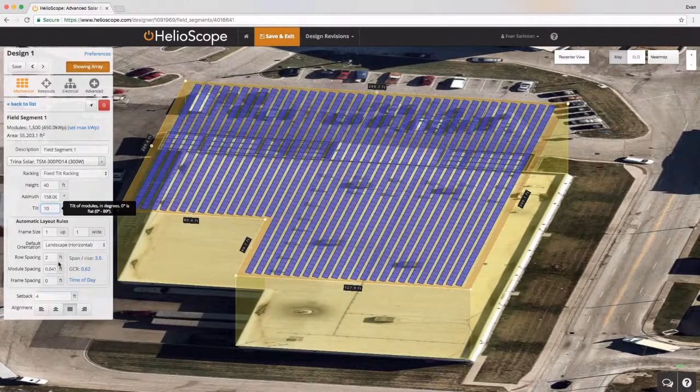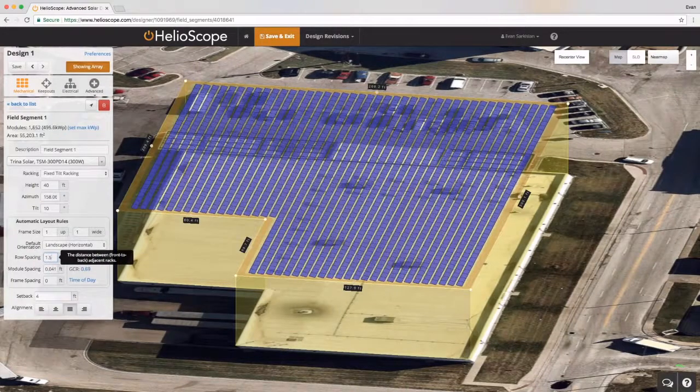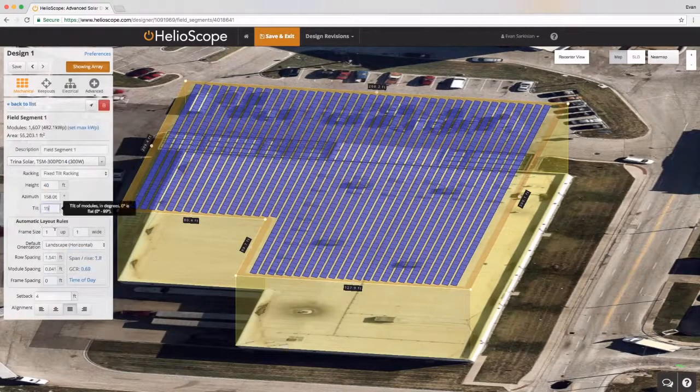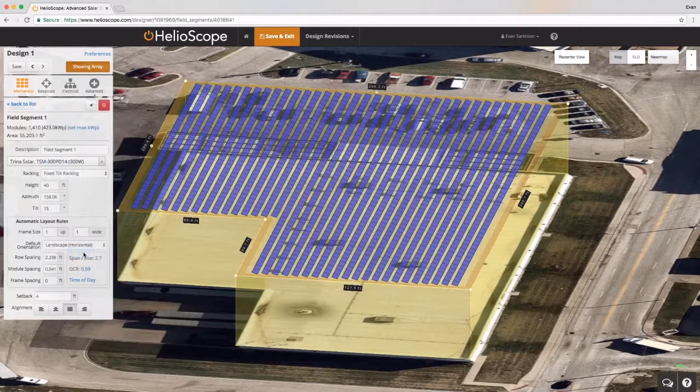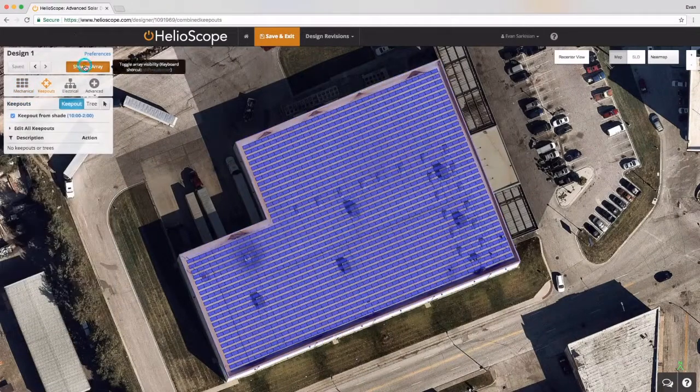There's a lot of open scope in there that they're not planning around, like the true nuances between running home run conductors in conduit throughout the array or going into a cable tray. That kind of stuff should be pointed out on a detailed construction document. You're not going to get there with HelioScope by itself.